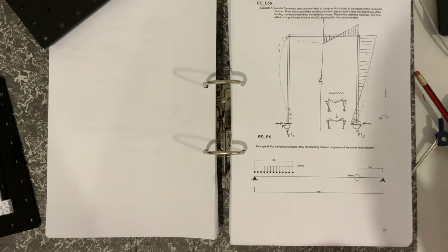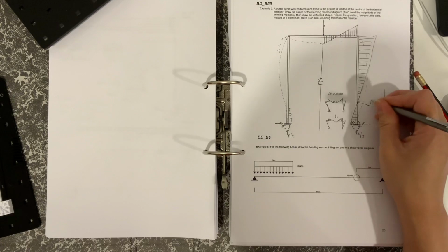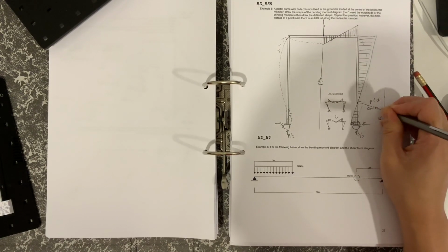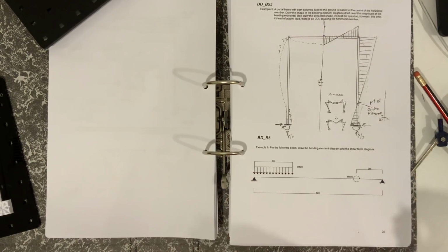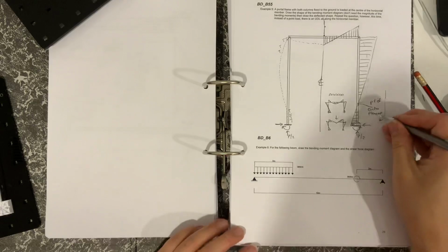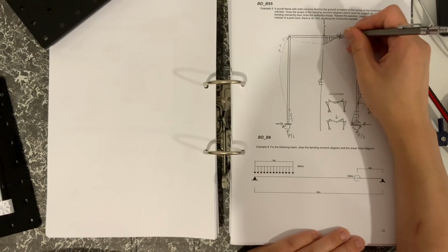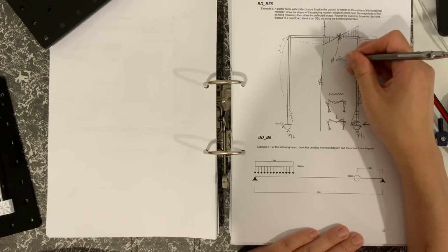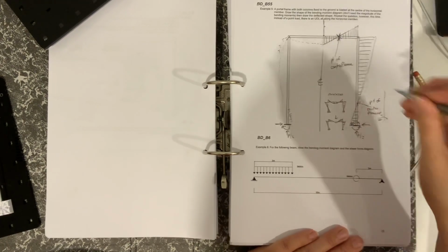Okay. I'll just make a point that where the bending moment is 0 is what's known as the point of contraflexure. If you look at the past exam questions, they tend to ask you to indicate the points of contraflexure. So that there would also be a point of contraflexure. That's where the bending moment is 0.